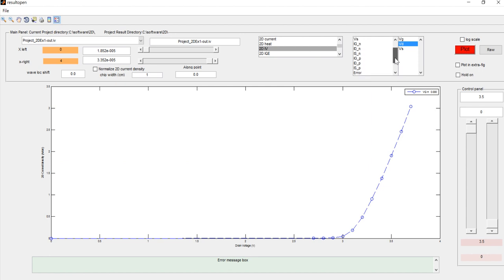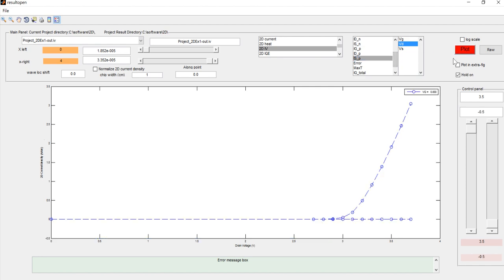And you can plot just electron current or hole current individually. So if you plot electron current, hole current of IS, yeah, see it's almost overlapped, and ISP, yeah, ISP is 0. Why? IS is an N-type contact, so that's not hole current. So ISP is 0. ISN has a value.